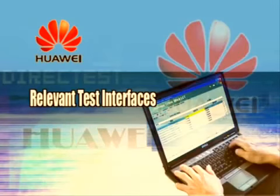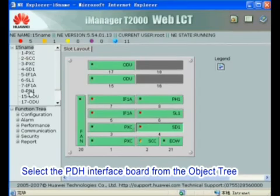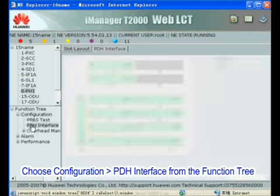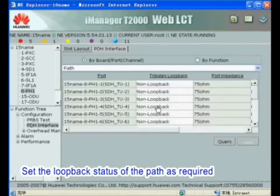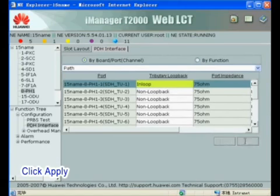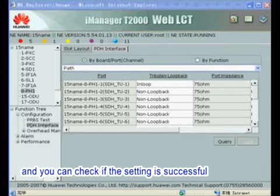5. Relevant test interfaces. 1. E1 Loopback. Select the PDH interface board from the object tree. Choose Configuration, PDH interface from the function tree. Set the loopback status of the path as required. You can select non-loopback, in-loop, or out-loop. Click Apply. Click Query, and you can check if the setting is successful.